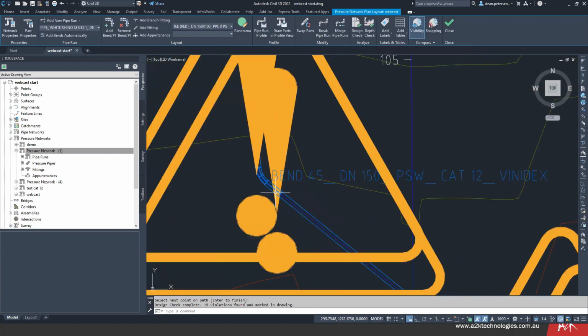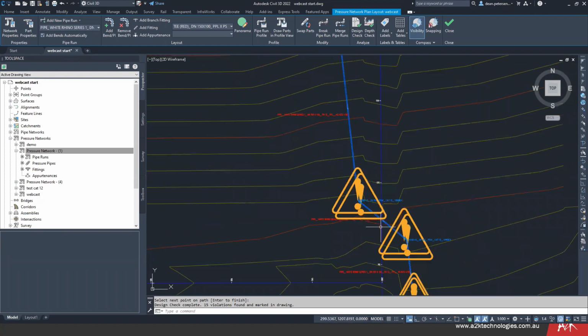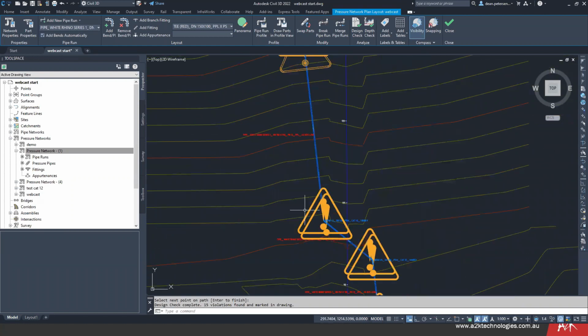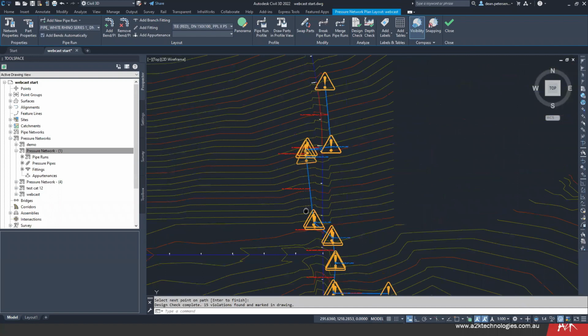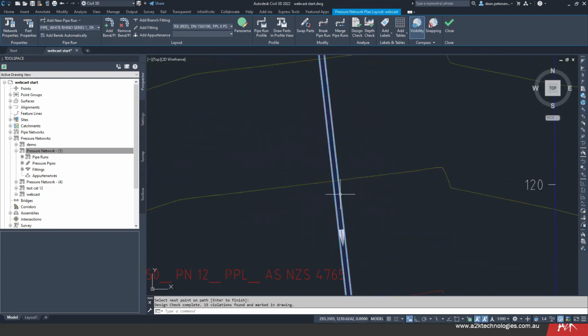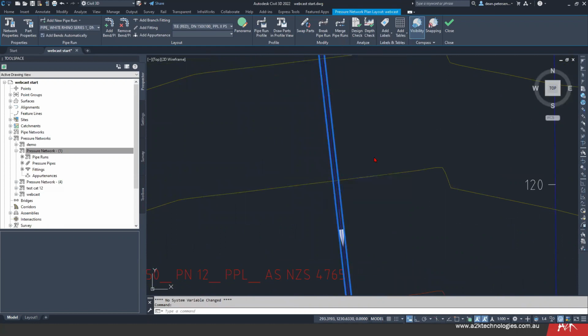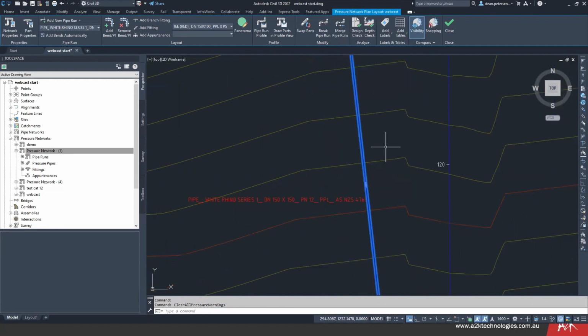Now, some of them, even if you've done them properly, there's a current deflection of 0.0002. So leaving it as 0 means you're always going to see these, even if they are actually nearest to straight or within the accuracy of AutoCAD. To get rid of those, you pick a pipe twice, right click and go Clear All Pressure Pipe Warnings. They'll all go away until we run it again.